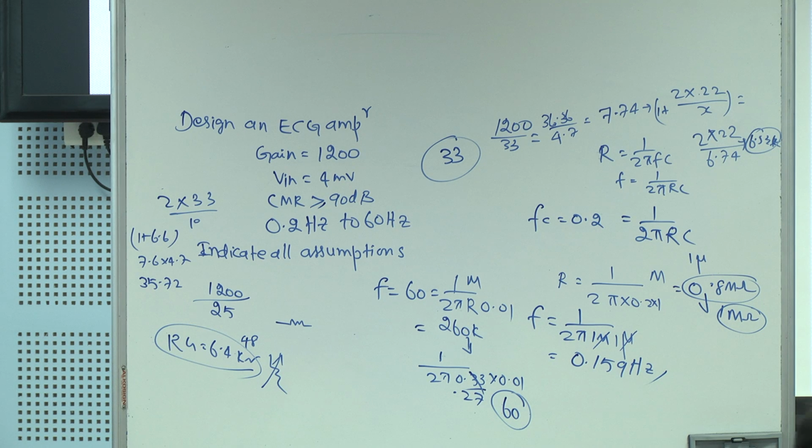Where are we? Okay, very good, you got it, 260 kilo ohm. So you can use 270 there. Yeah, 270 is standard. So we calculate, it's fine. So you say equal to, put an arrow, because 270 is standard. Very good. Okay, so do this for the other two stages, students.